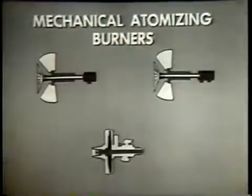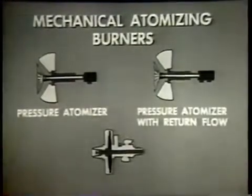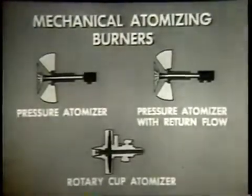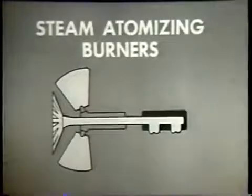combustible mixture. Although all burners perform these two functions, atomizing the oil and mixing it with air, different types of burners atomize the oil in different ways. Most burners are mechanical atomizing burners. Some mechanical atomizers are the pressure type. There is also a return flow pressure atomizer. Another mechanical atomizer is the rotary cup type. A few burners use steam atomizers. In this film, we will see how these different types of burners work.